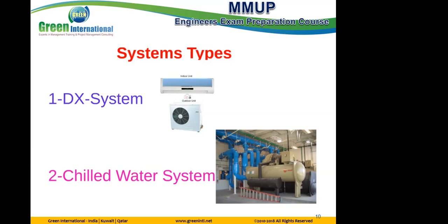And this water is working in a cycle, the same as the simple refrigeration cycle, but it is a closed cycle for the water, and this closed cycle is in contact with another cycle which has refrigerant, to exchange heat between refrigerant and water. And this water goes to contact between water and air through the evaporator to make heat exchange for this part. Is this clear, the difference between the DX system in HVAC and the chilled water system?